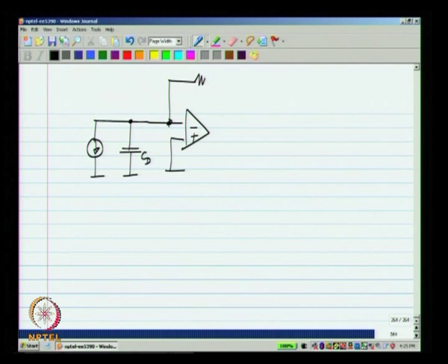We know that ringing appears when we have too much delay in the feedback loop, that is one way to think about it, or when we have a low frequency parasitic pole and so on. Now, one way to counter the effect of the pole is by adding a zero. Now, from the output of the op amp to the input, we have a first order system